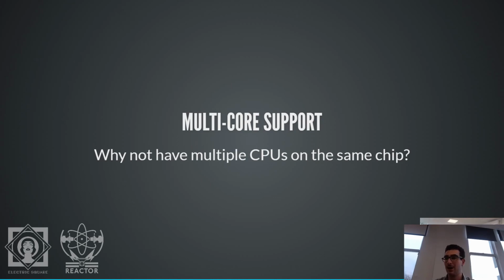Instead of having deeper pipelines, and all the trade-offs and design complexities we described earlier to mitigate the effects of those, why don't we just say, let's not worry about having super high clock cycles? Let's have slightly smaller pipelines, reduce loads of complexity, and now just have multiple CPUs on the same chip, right? Because we just have to make the pipeline a tiny bit shorter.